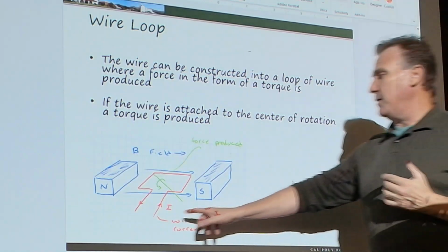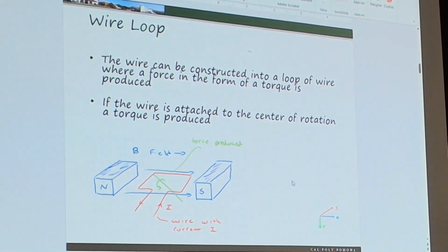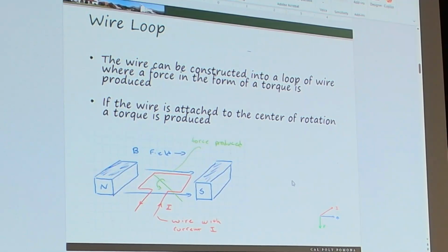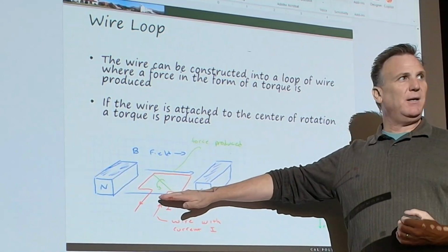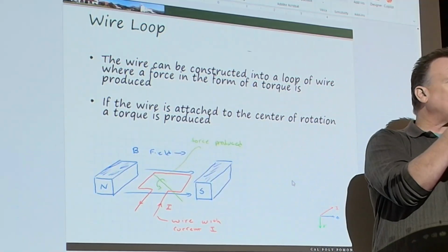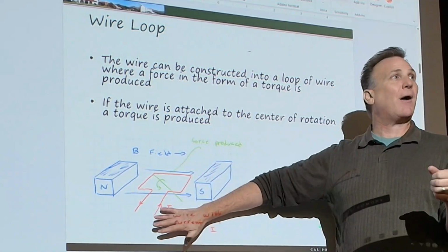Now, the wire in here has to dissipate that energy sufficiently to not burn up, right? We've heard the expression, my motor's burned up. Is that reality? You probably hear that colloquially, but is that a real expression? You tell me. Yes. Because if my motor is exhibiting all of this energy and trying to get rid of it, but it can't physically move because it's stalled or something's holding the end of it, and I'm applying voltage and current, because that's electrical power,